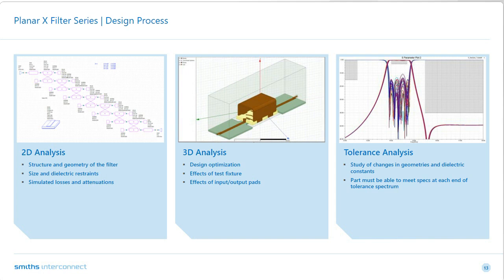First is coupling bandwidth. If the filter is narrowband, half wavelength structures allow for asymmetrical responses and quicker time to market life cycles than other geometries. As we start to get into more wideband responses, quarter wavelength resonator structures must be used. There are of course some trade-offs between the two topologies, where half wavelength resonator structures produce a symmetrical response.